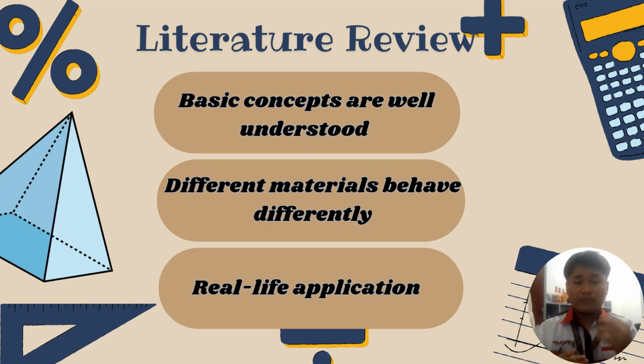They are made from high-strength steel wire that can safely elongate under load without permanent deformation. As engineers, we apply an adequate safety factor to ensure the stress stays below the yield strength, preventing any catastrophic failure. That's all from me.